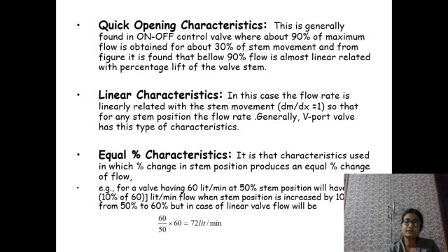And equal percentage characteristics. This is the characteristics in which a percentage change in stem position produces an equal percentage change in flow. Then what is the difference with this linear characteristics? Say for valve having